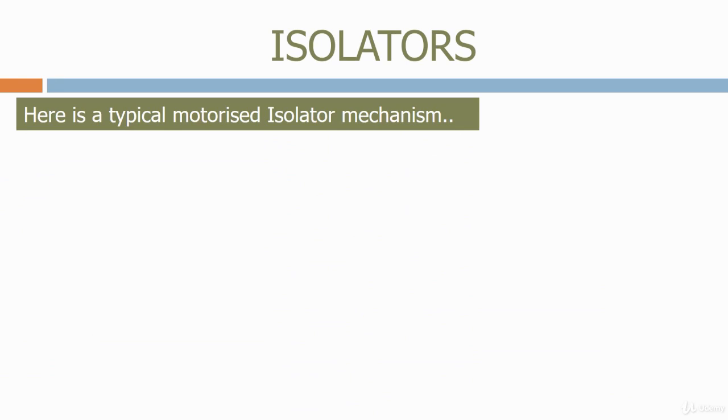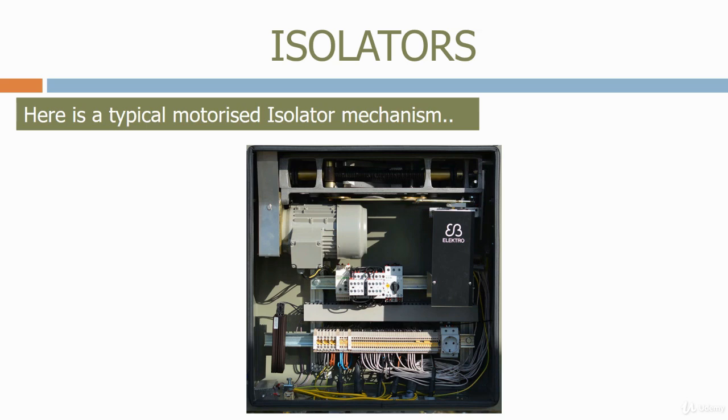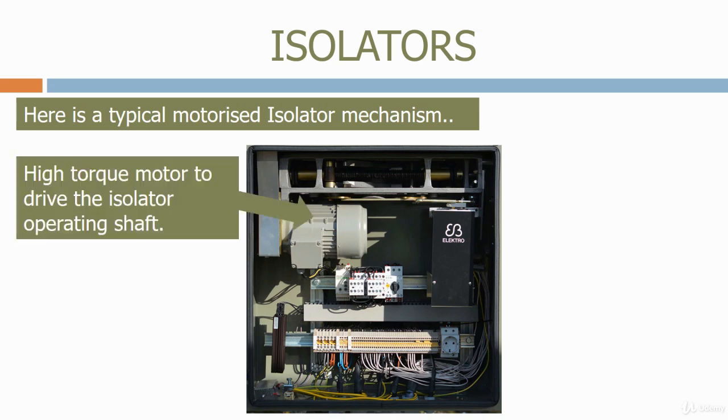Here is a typical motorized isolator mechanism. Firstly, we have a high-torque motor to drive the isolator operating shaft. The isolator drive mechanism and conductors can be substantial and need a high-torque motor to ensure that when the contacts open and close, this is done in a firm way.